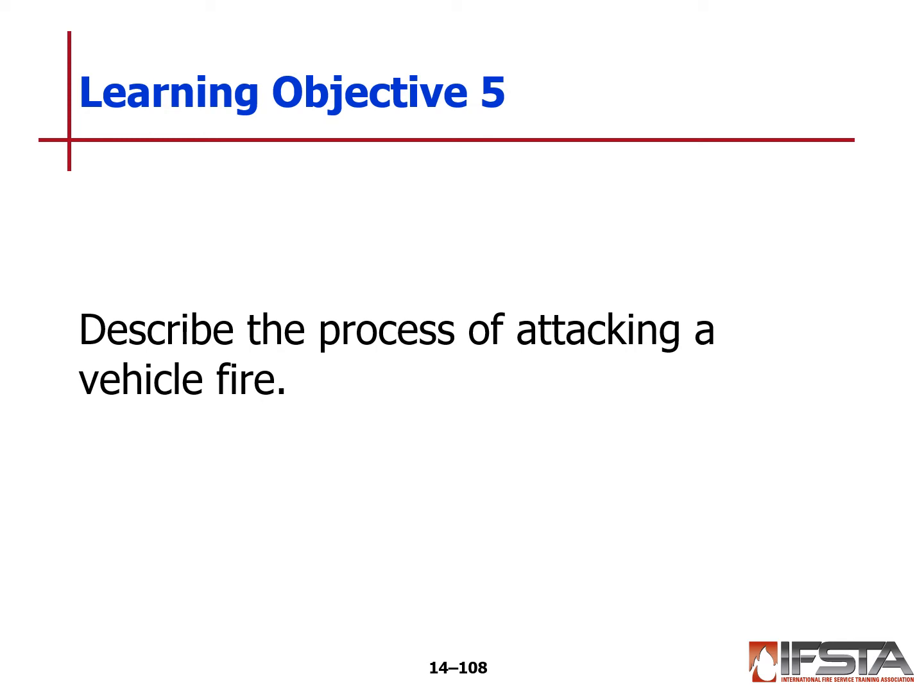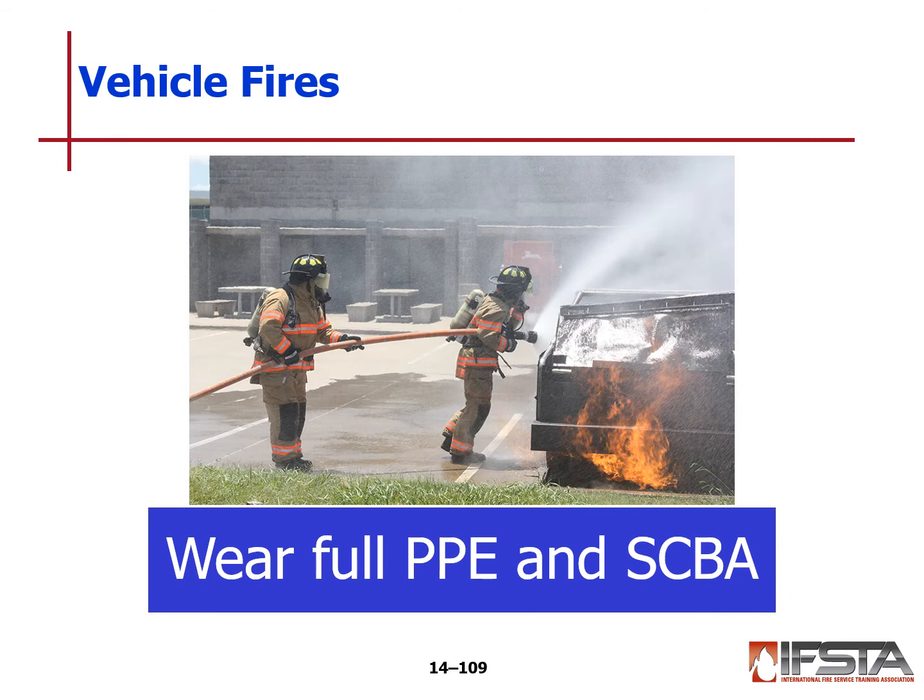Next is the process of attacking a vehicle fire. One of the things to note is we want to wear full PPE and SCBA during all operations with vehicle fires. We often think that because we're in the open, it's not a concern, but there are a lot of plastics, foams, and rubber materials burning in our vehicle and even the engine compartments.